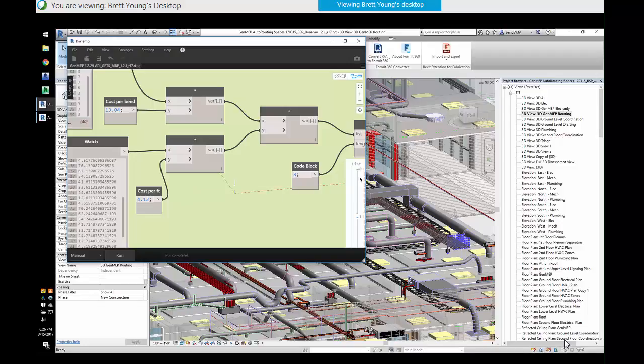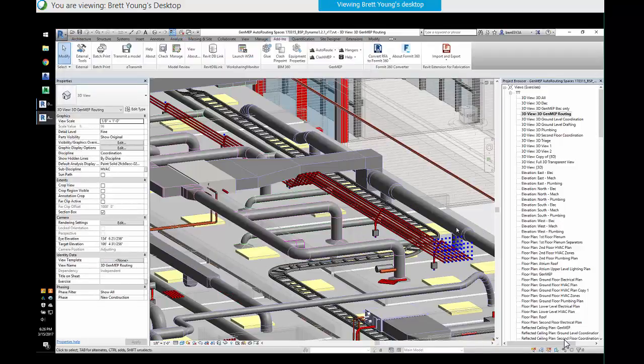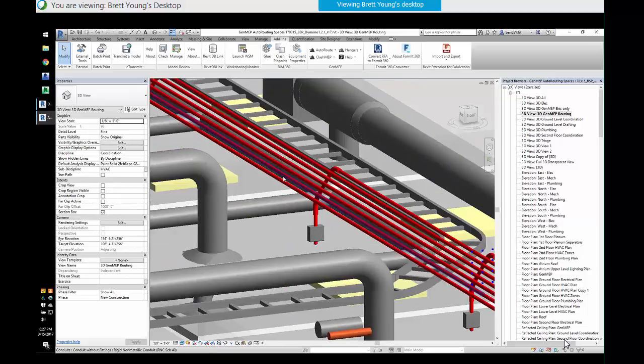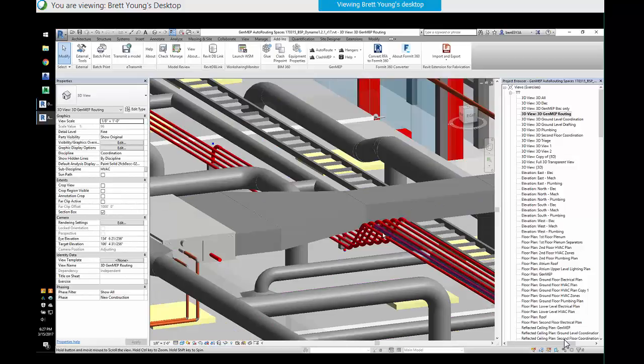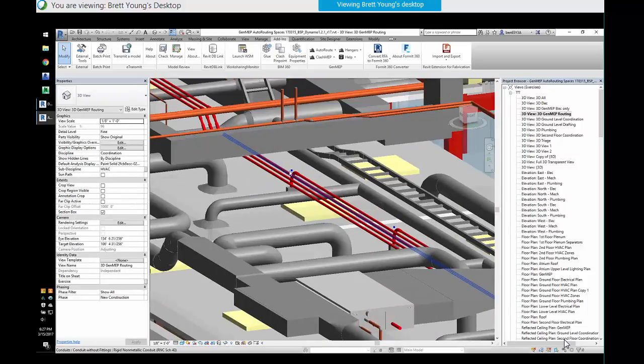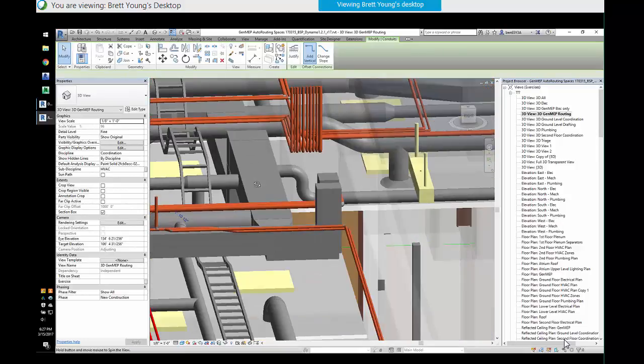So over here in Revit, you can see that the blue points were my start points. The elevations above the bottom one were determined not to be the optimal solution, so I deleted those routes totally, and we picked the bottom elevation and routed it for real in Revit and kept that solution. So as you can see, these 8 routes work their way across. Each one by one, they drop off into the J boxes as they hit their targets.